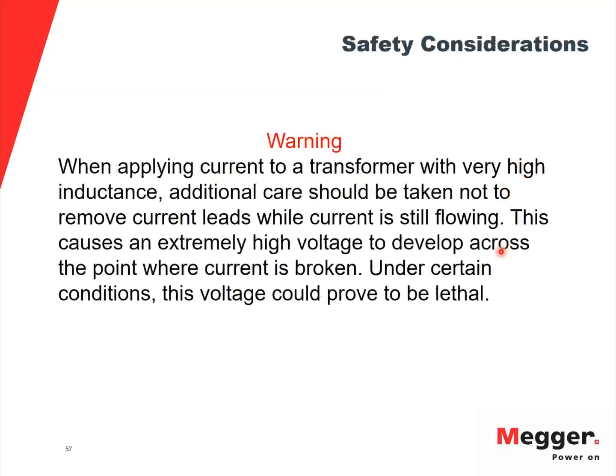Once you perform the test and have got good readings, it is very important to discharge the specimen, or discharge the winding. You know that an inductor stores energy, which means that if I don't dissipate the energy and I take the leads off, that whole amount of energy is going to dissipate where the connection gets broken, and it can develop a lethal amount of voltage, which could be dangerous to the transformer or the person operating the leads.